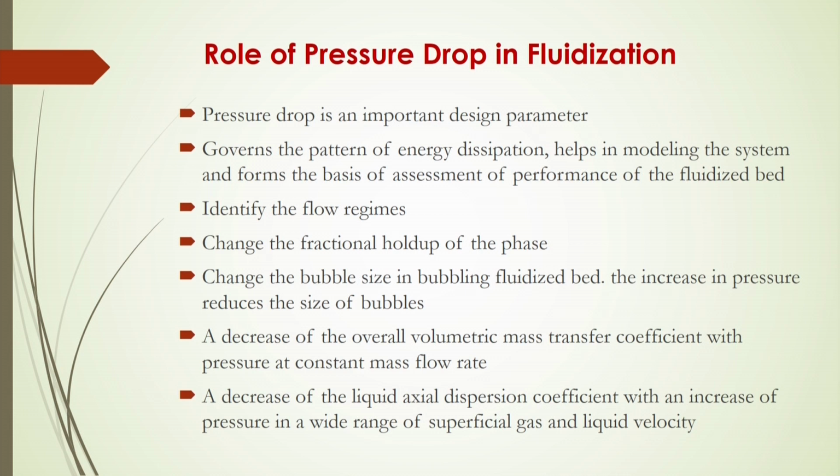the fluidized bed. And also this frictional pressure drop will identify the flow regimes, because different pressure drops will give you different types of flow regime maps. So, change the frictional pressure drop, you will get different flow regimes, and based on that you will see that there will be a change of frictional hold up in the fluidized bed.